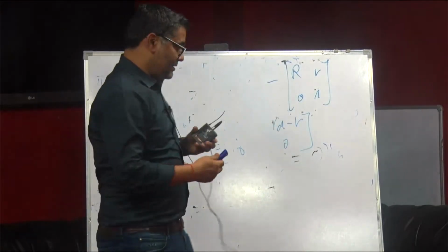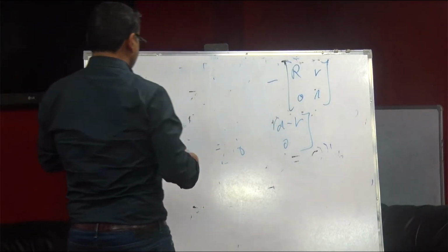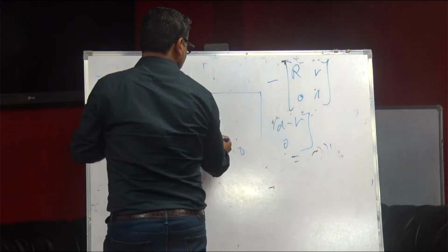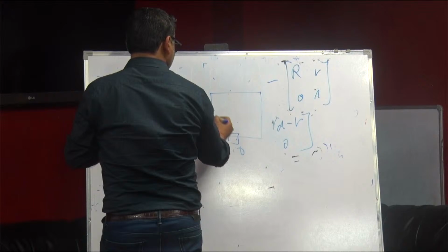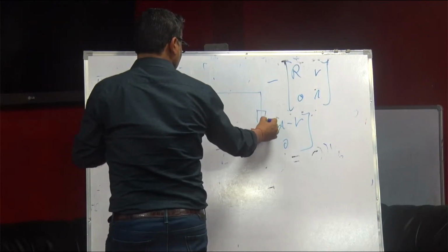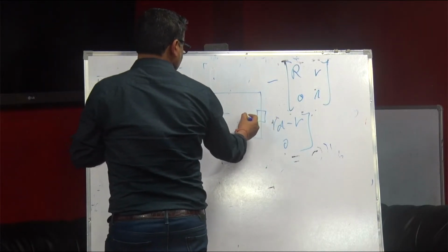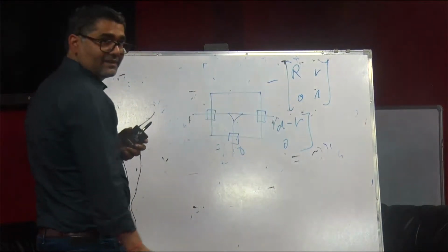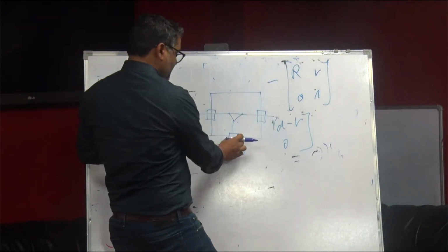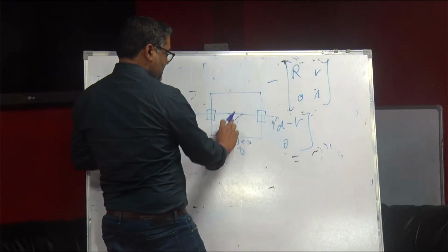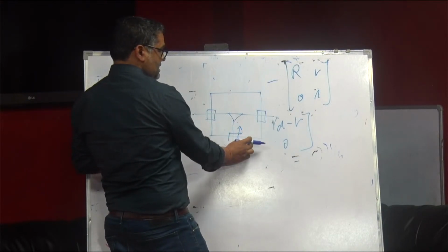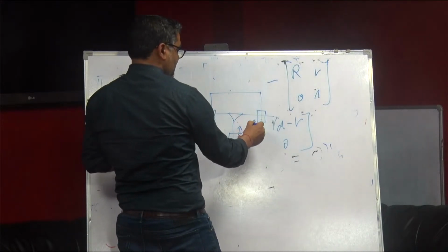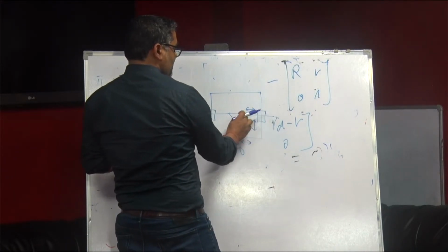So here we are going to make a planar parallel manipulator. Here you can see it is a structure like this one. There is one translation, second translation, third translation, and then another translation, another translation, another translation. So it is connected with the end effector. Here, this can translate and this can also translate. This translation is the powered one, meaning you can give some power and it translates. Here also it can translate and this part also translates.